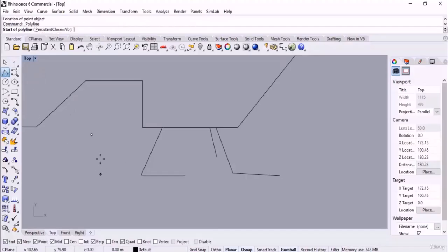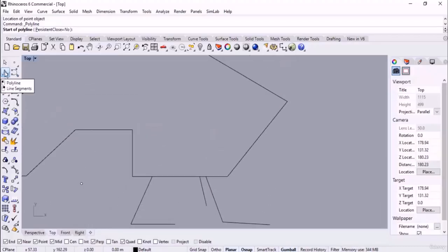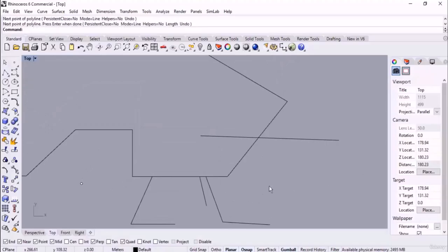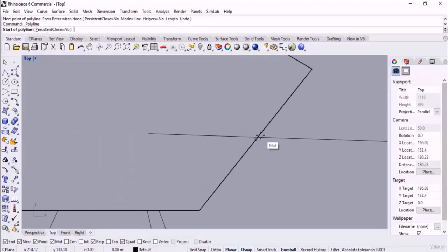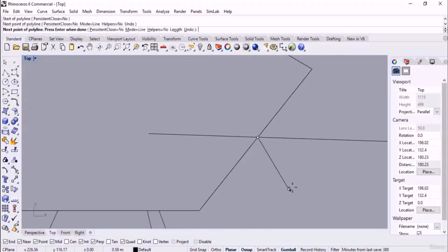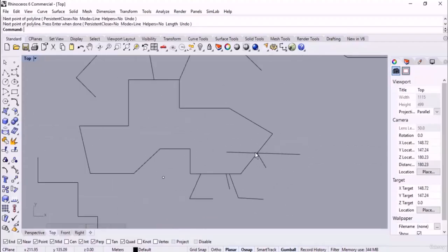And about points, it constrains the marker on the points. As you can see, check this out. And the midpoint object snap, I explained it. Center is used for the circles and the curves, and it gives us the center of them. INT or intersection object snap gives us the intersections. If I sketch a line like this, then we can have the intersection between these 2 lines. As you can see, here we got the midpoint, and I activate intersection like this, and then it constrains the marker, so we can start a line from there and sketch the line from the intersection.